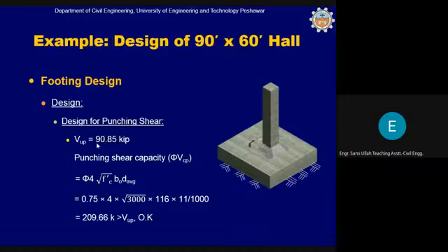So the assumed thickness is enough, or even slightly more than what should have been assumed. If you want to, you can reduce it from 15 inch to 12 inch, so there is a slight margin of reduction in the thickness of the footing. Anyway, we are not doing this in this example. We keep our thickness equal to 15 inch.